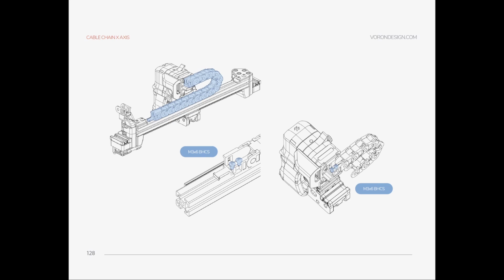And after that, start crimping from here and run your wires, and you will access wires in the electronics chamber. Just do the routes and run the wire with those routes, and once you reach where it should be connected, just cut it, crimp it, and plug it. That's all.